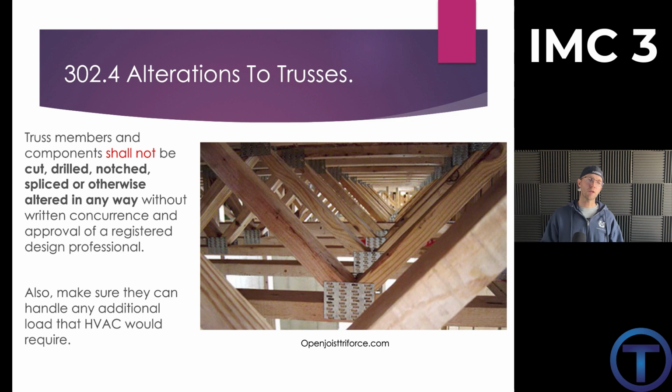302.4 talks about the alterations to trusses and states that we shall not be cutting, drilling, notching, splicing, or in any other way altering trusses. Now that goes for roof trusses, but also floor trusses. The other thing that it states is that you want to make sure that those trusses can handle the weight of any additional HVAC equipment.